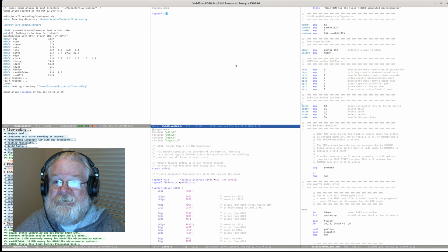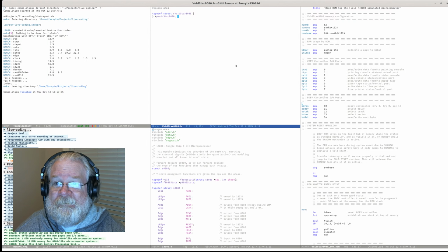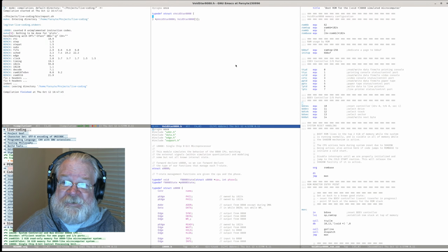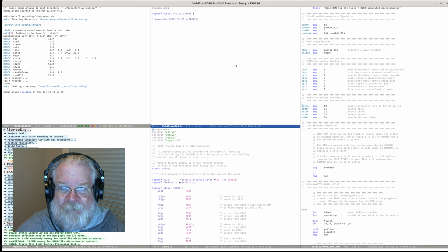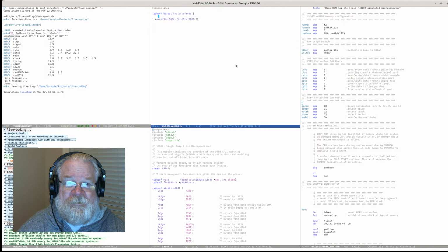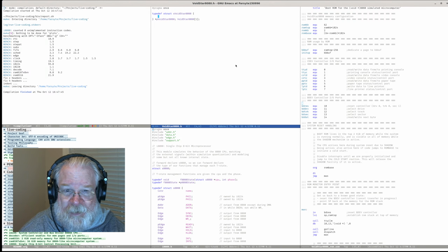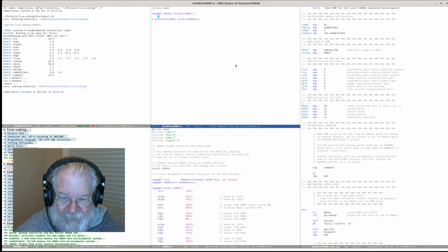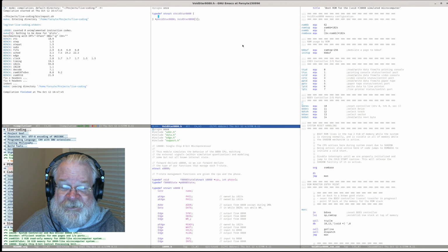So typedef struct VoidStar 8080, like that. And this is actually going to be S VoidStar and P VoidStar, because as long as I'm simulating, I may want to simulate multiple of these in parallel. I may want to have 8 of these machines spread across my desk talking via a network port someday. So we're not going to use any ideas that say there's only one. Now, the one thing that we are constrained about is our system clock, our simulation clock, which is stepping in sync across all of these guys. That's just because clock is itself a singleton.